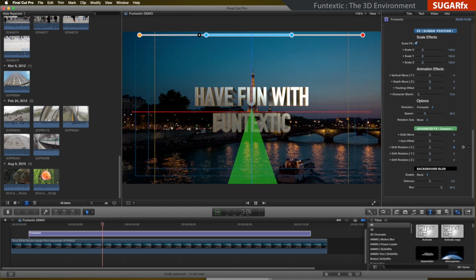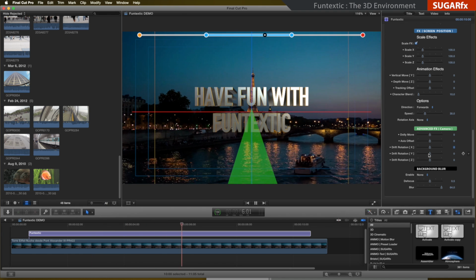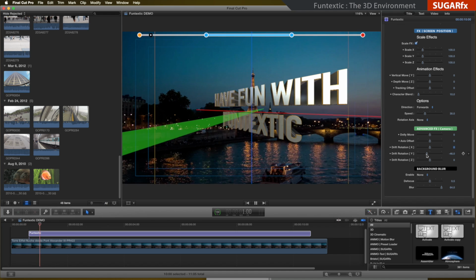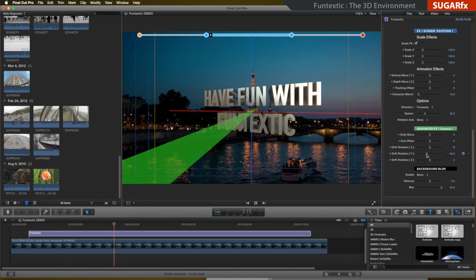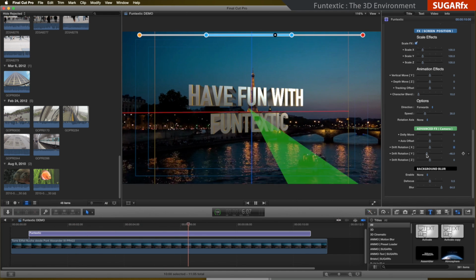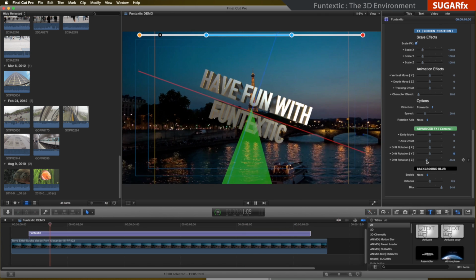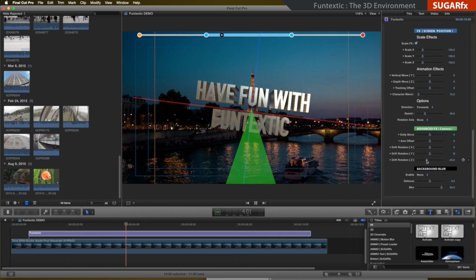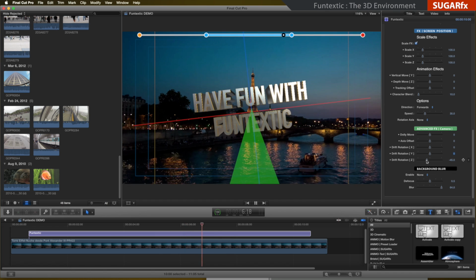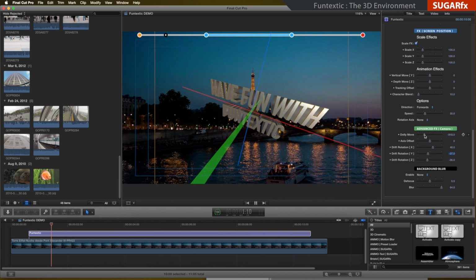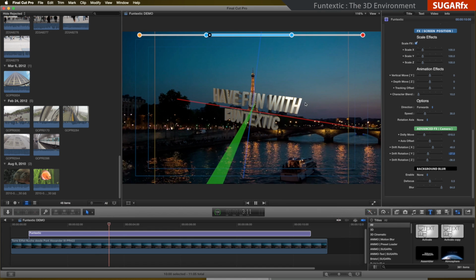This type of animation will definitely affect the setups you have done to your start, end, and screen positions, and you may need to adjust them to compensate for any offsets. It is strongly recommended that you do your 3D environment moves first and before you set up your start, end, and screen positions, or you can use lower values to avoid upsetting your current setups.